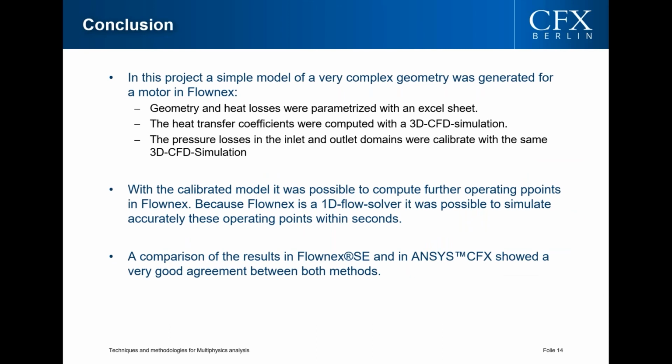Okay, and actually I'm already at the end of my presentation. Just as a summary, in this project we generated a very simple model for a very complex geometry for a motor in the software Flownex. The geometry and the heat losses were parameterized with an Excel sheet. The heat transfer coefficients, which are very important for the accuracy of the simulation, were computed with a 3D simulation, but only for one operating point.